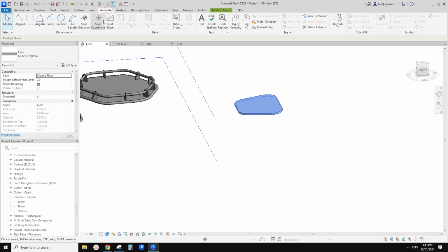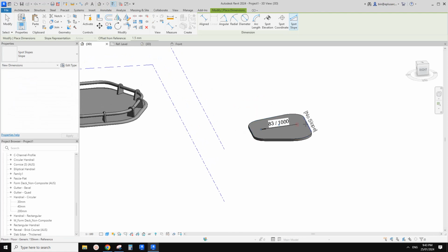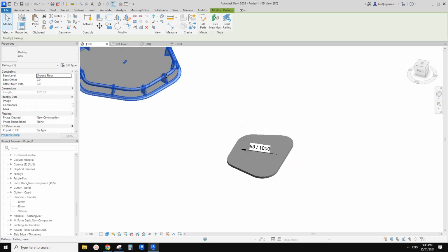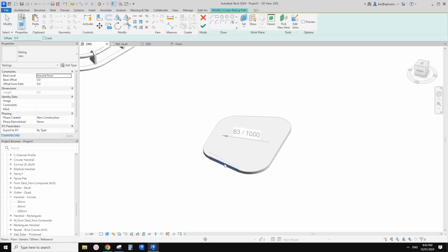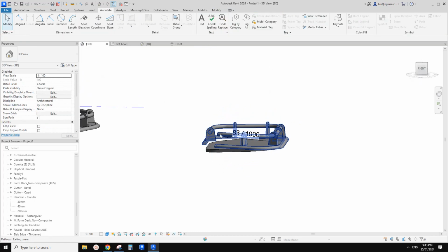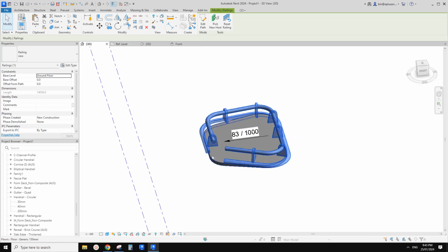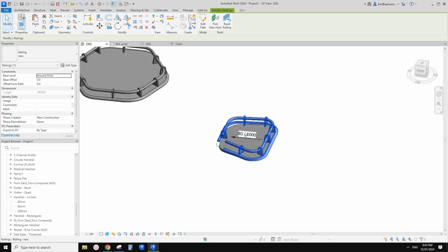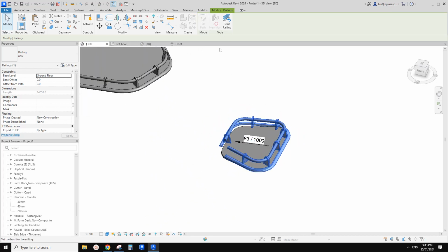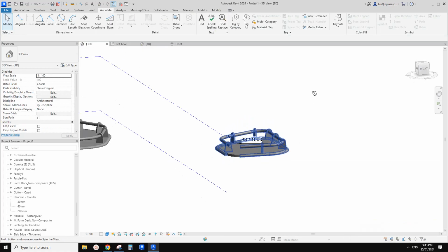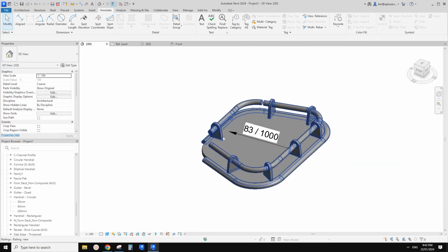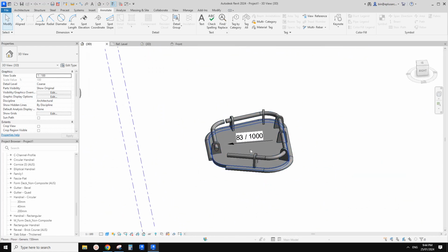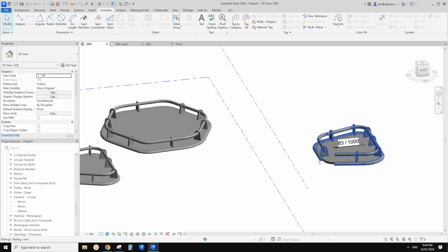So I'll just do a slope arrow. Okay, and select this CS, and we can pick line, tab, and create. And then, looks like it's broken, probably because there's some reason. And use pick new host and pick this floor. So it's trying to, not too bad, but yeah, it's broken here for some reason.